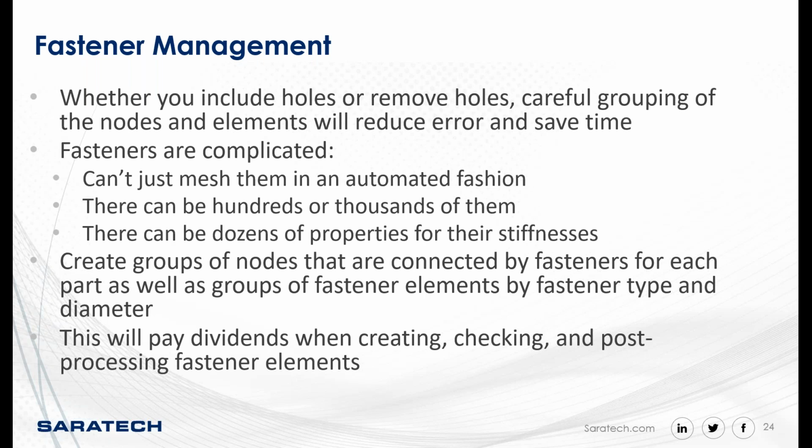So it's a good idea to create groups of nodes that are connected by fasteners for each part, as well as groups of fastener elements by their fastener type and diameter, so that once you've created all of your fastener elements and you want to easily go in and extract their loads, go off and do your strength calculations with them. If you have organized everything very carefully, your chances of leaving out fasteners are greatly reduced, and your post-processing time for extracting the loads will probably be much better. So organizing everything very carefully with groups or even layers, I tend to prefer groups, will pay dividends later.